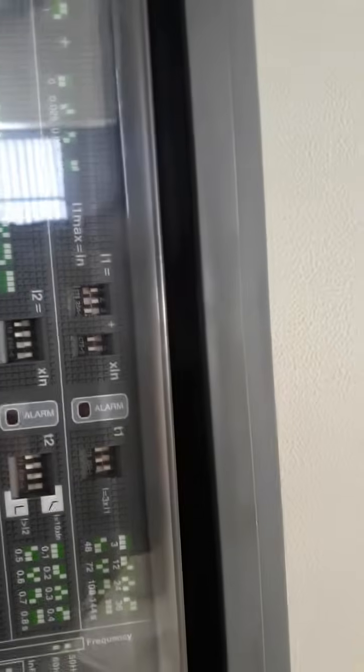It means the value is 2. Okay, so 2 means the nominal current is 1600 amps. So 2 into In means nominal current. So 2 into 1600 means 3200 amps coming. Okay, so when the short circuit current is going to reach 3200 amps, the breaker automatically trips.